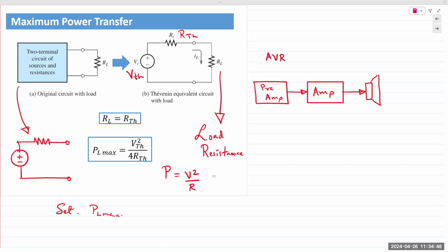So the question being asked is, how would we split up if we wish to perform source transformation on a large circuit? Now, there may or may not be a current source in the circuit. There could be maybe hundreds of voltage sources. It doesn't matter whether it's a voltage source or a current source. If we wish to split up a voltage source, you're absolutely right. Yes, we have to maybe draw 2 lines and cut it out. We might even have to draw 4, because if the voltage source is in the center with components on all 4 sides, we have to figure out where it is connected in the circuit. And that's why it's tricky.